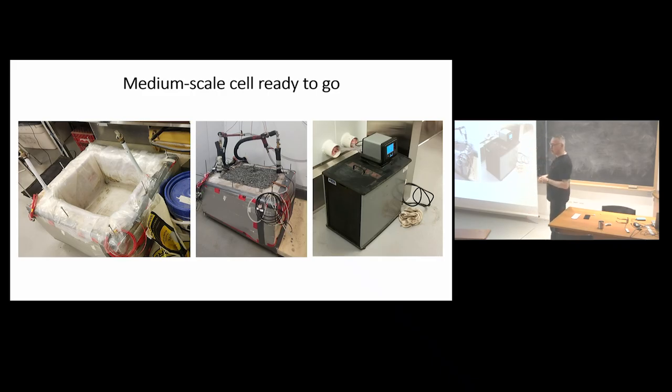It is called pre-thawing before construction. So we arrive, we thaw the permafrost, we remove the water, then we consolidate. All this we do in the lab, but in the field, we're starting this summer at the field scale. We work with big excavators and stuff like that. And then we refreeze it. So you have a very consolidated slab, ice poor, and that can sustain buildings, for instance, or things like that. And because it will settle, we fill it back with non-frost susceptible material.